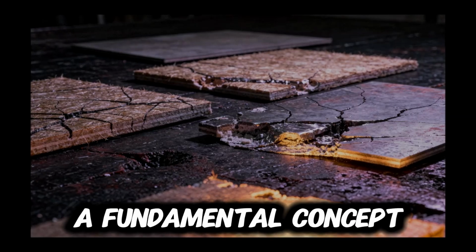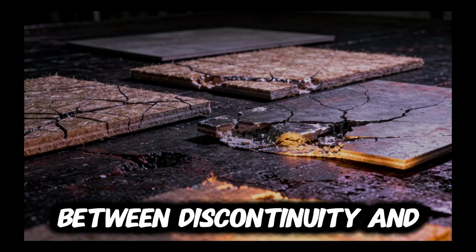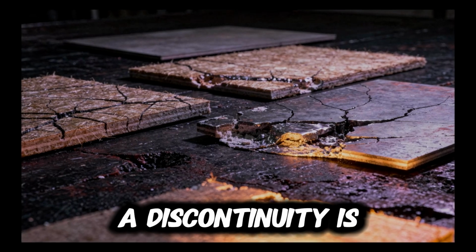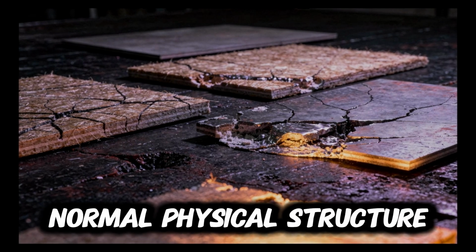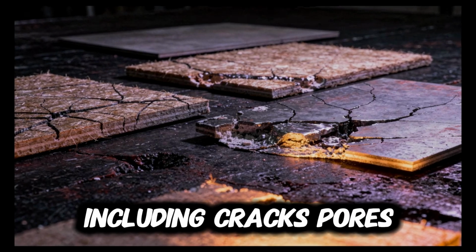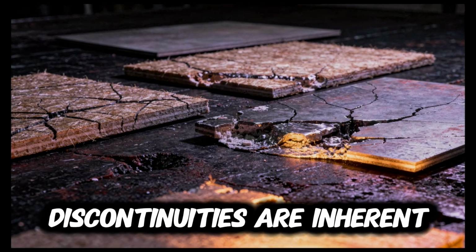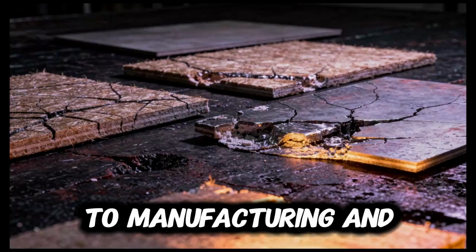A fundamental concept in non-destructive evaluation is the distinction between discontinuity and defect. A discontinuity is any interruption in the normal physical structure of a material, including cracks, pores, inclusions, seams, or geometric deviations. Discontinuities are inherent to manufacturing and service.